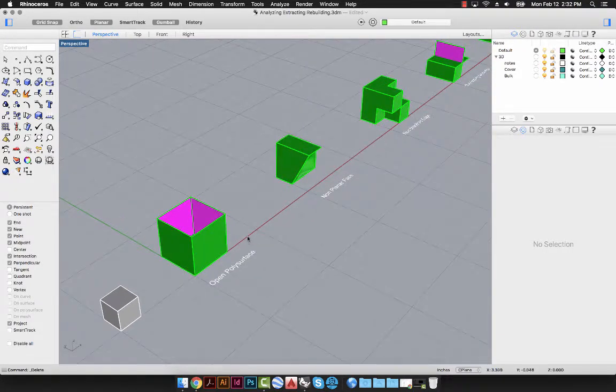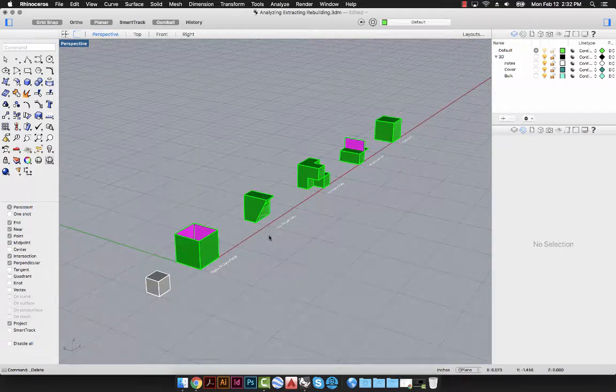The next is the object visibility palette. I've noticed that when I watch many of the students modeling, they're not using their visibility palette. So I'm just going to go ahead and right click, pop open my visibility palette, and there are just a couple of commands here that I wanted to show you really quickly. First of all, I can hide and show, and then I can invert selection and hide objects. And then I can swap the hidden and visible objects. So I have some objects hidden, so I'm just going to swap them out.